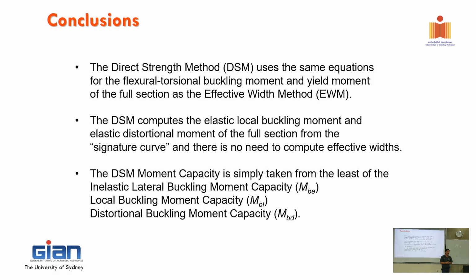So far, we haven't got the evidence or the tests showing the interaction between distortional buckling and flexural torsional buckling. So research is still going. And remember, the other interaction is local buckling and distortional buckling. Sometimes you remember the cross section, when you click the button, yes, local buckling and distortional buckling, right?